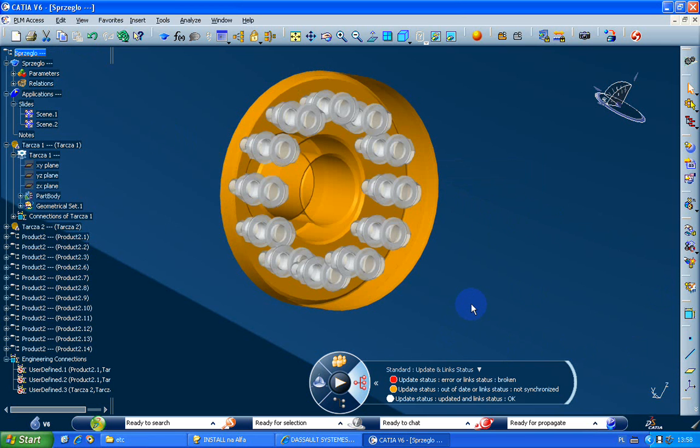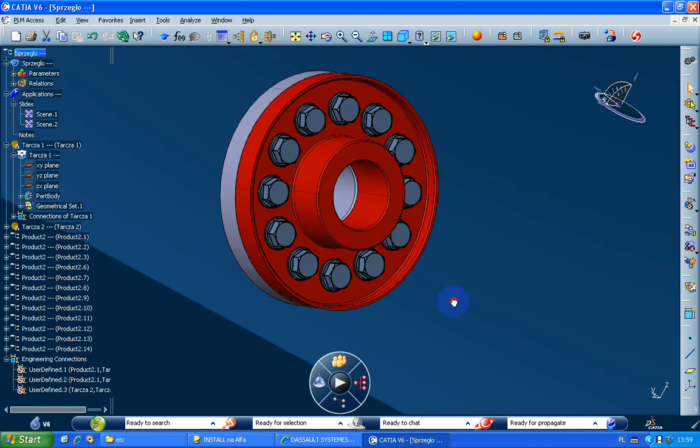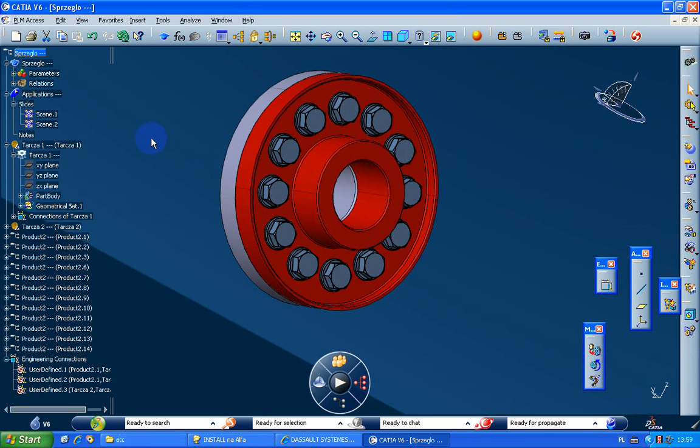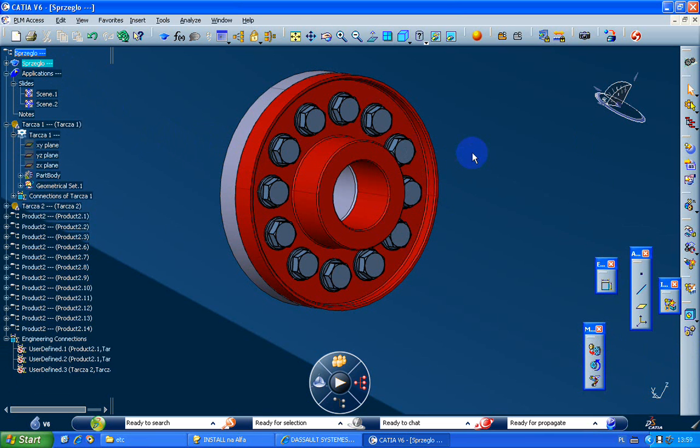What can I see? The current status is in red. In CATIA you can scroll the list, and in the list you can see to freeze, to release, to remove. In fact, CATIA will automatically filter for you the list of possible changes. You can see that I could not put it in obsolete status. Here I can see when my arrows are green, it means that I can perform these maturity status changes.